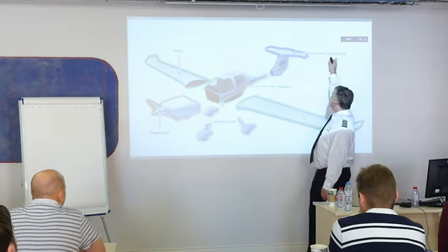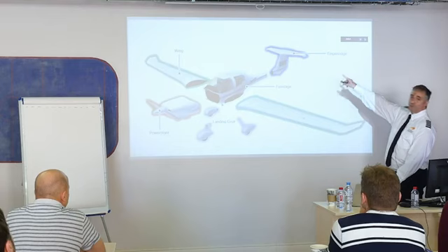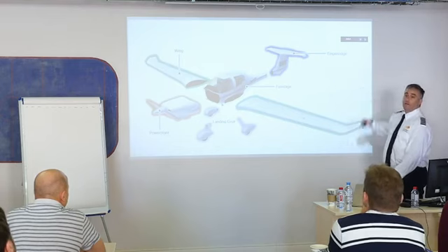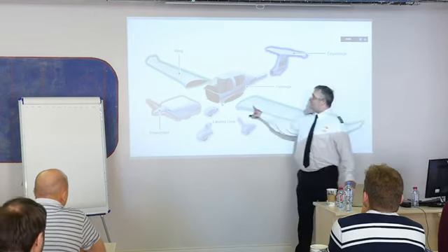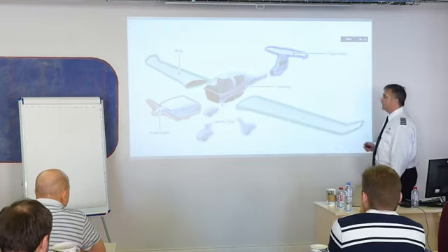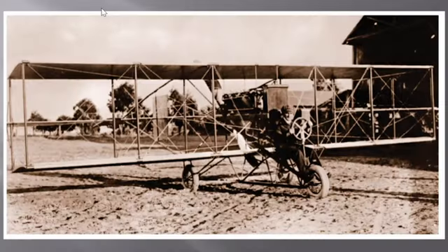It's listed right there. That's just the tail section of the airplane and includes vertical stabilizer, horizontal stabilizer, a rudder, and an elevator. The wing, these are typically attached together and through the fuselage with a spar. The power plant and the landing gear. Those are your major components.